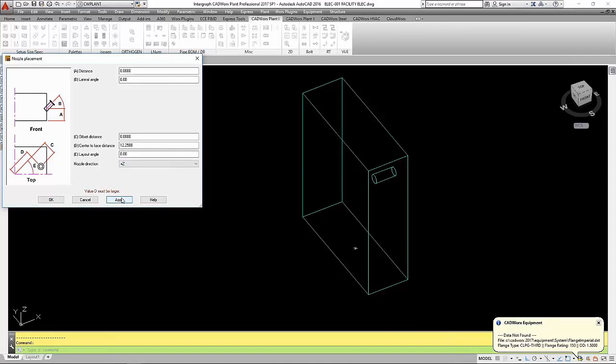It's telling me I need to have a larger D value here, so it won't let me get in trouble. So it's asking me to basically get that nozzle outside the boundary of the box. Right now it's inside the boundary, so I need to change this boundary. Go to 24, that'll get outside a little bit. So now I've got the nozzle coming top dead center.